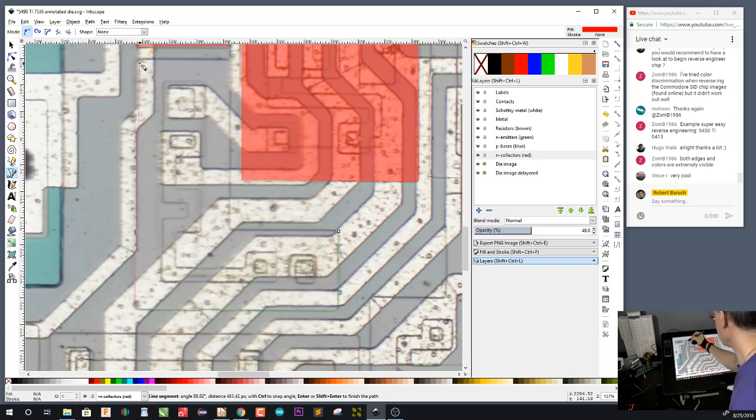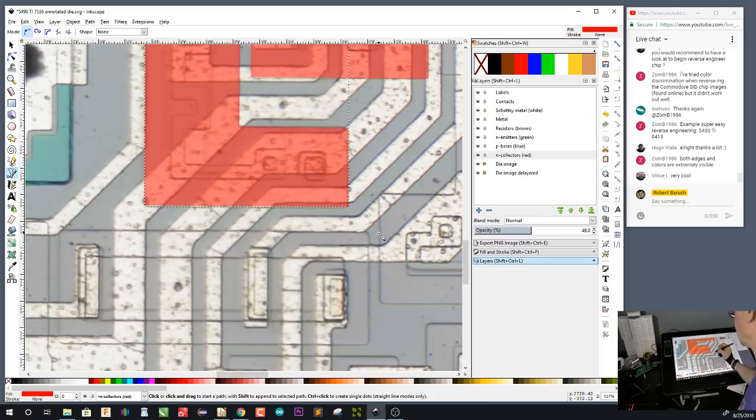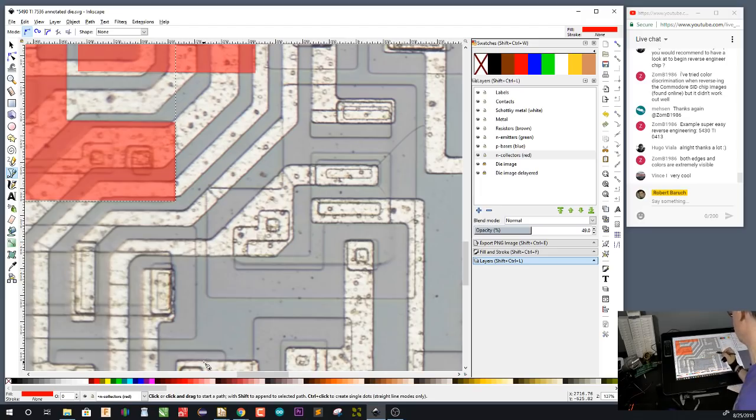There are some implications with respect to integrating a resistor into a transistor, but for our purposes in a schematic, it's just going to look like a resistor connected to the base of a transistor. Same thing over here. You can see that here is the base region. Here is the emitter. Around it is the collector. And here's this strongly connected connector thing over here. And then there's this squiggly bit running off of the base. That's actually just a small resistor.